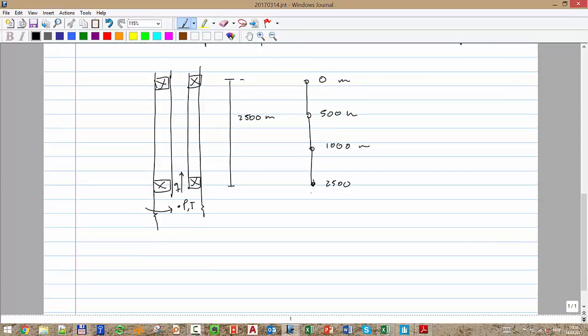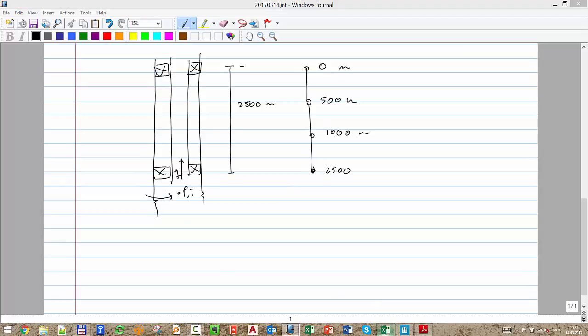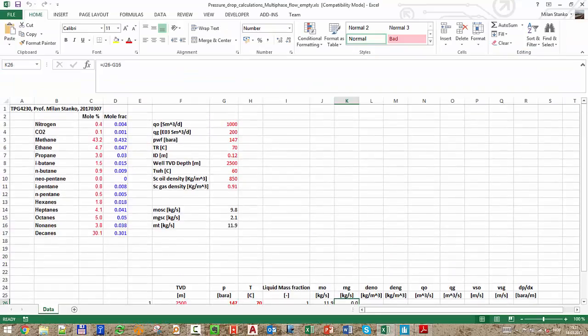So we are departing from that point, Q and pressure and temperature, and we want to calculate what will be the pressure in all the other points in the tubing. And the values that are given are standard oil and gas rate, bottom hole pressure, reservoir temperature, internal diameter of the tubing, the true vertical depth, and the wellhead temperature. Okay, that gives you already the gradient. As I explained in class, that procedure is for pressure only.